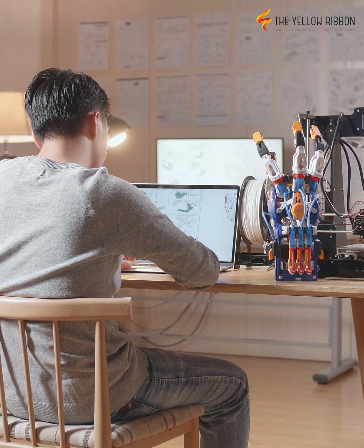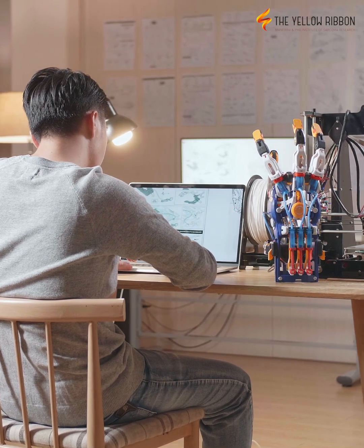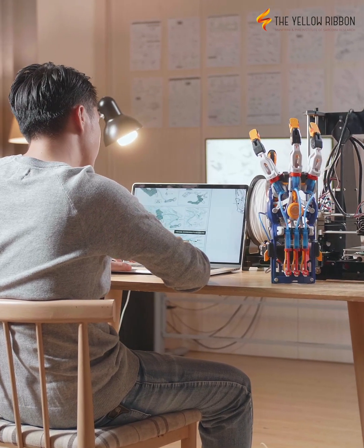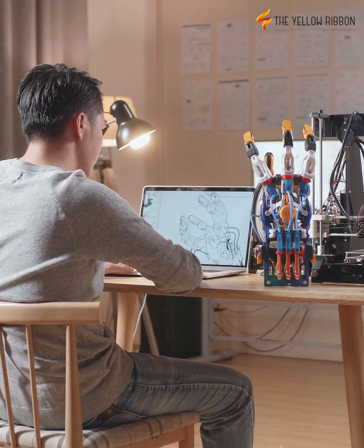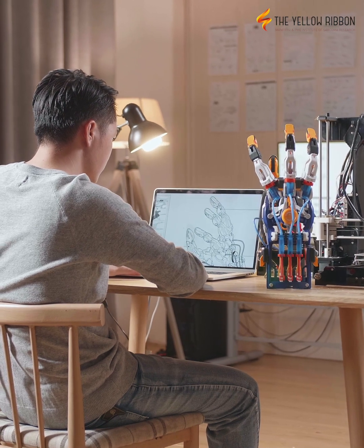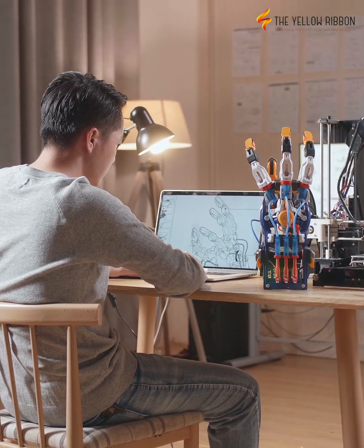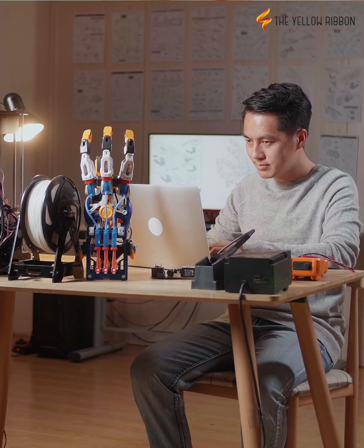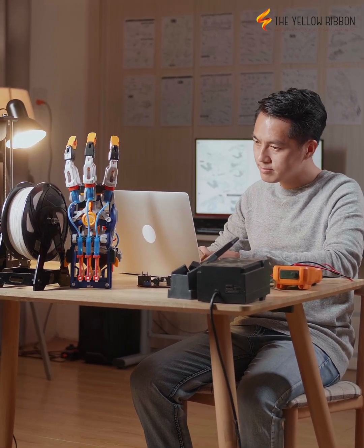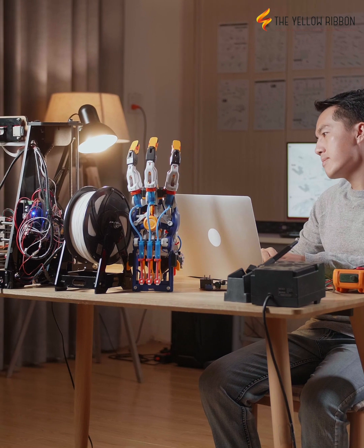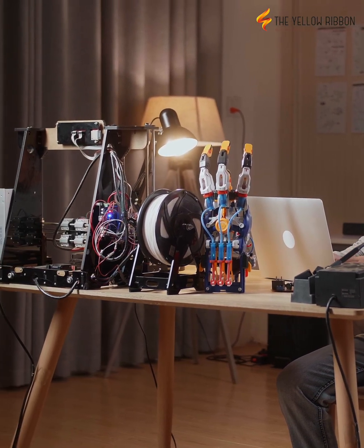After this step, using different software, errors are figured out, meaning before printing, the saved files are checked for errors or mismatches with respect to the original piece or the sample. Now, after which the file is processed using software in such a way that it converts the model into thin layers. Now, after this, there's a code that is generated known as the G code. Basically it has instructions that are tailored to a specific type of 3D printer. Now, once all of this is done, finally, the model is printed using 3D printers.